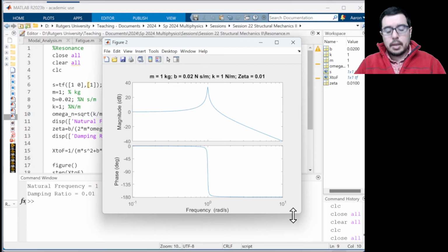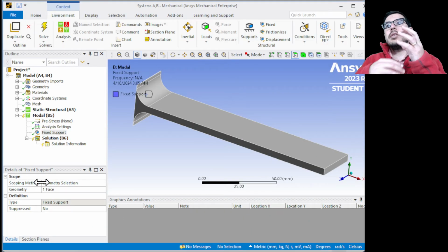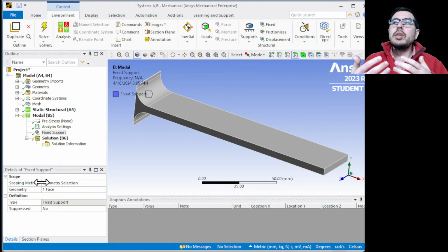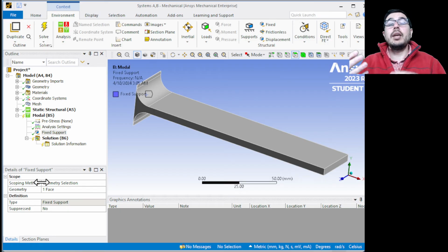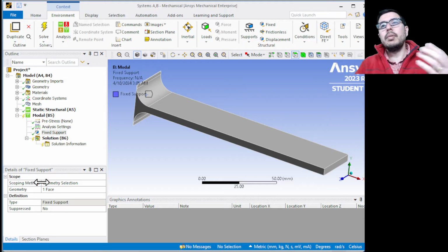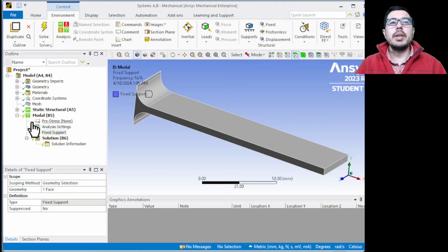So in Ansys, there are ways to change the structural damping, the solver damping. Actually there are 3, I guess, or material damping. So structural, material, and numerical.